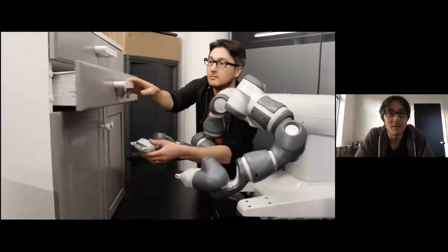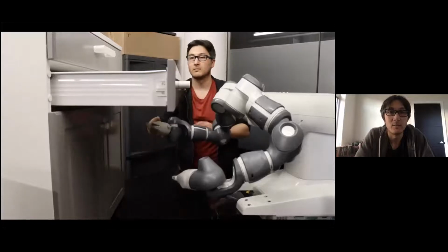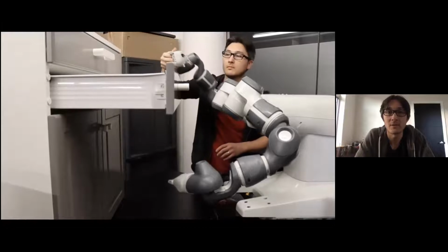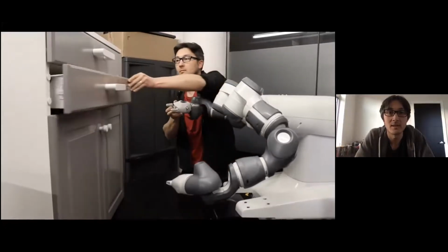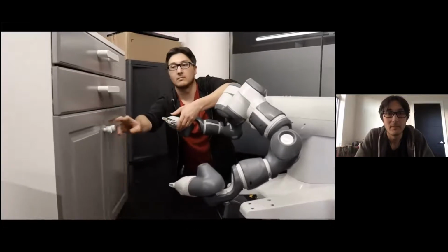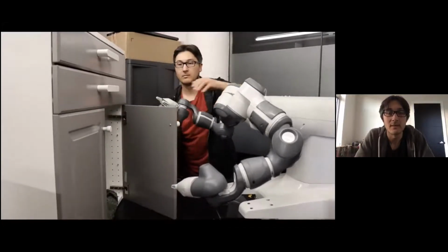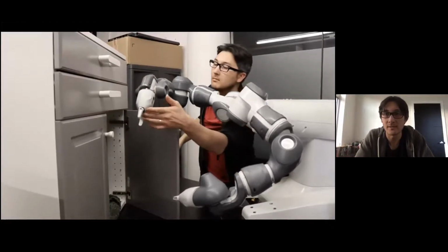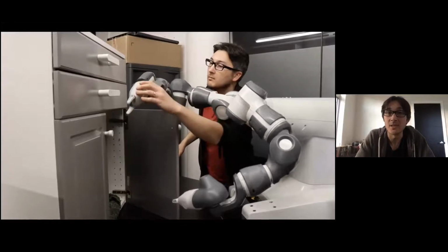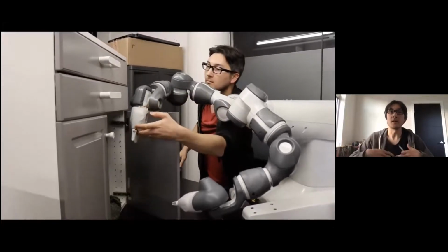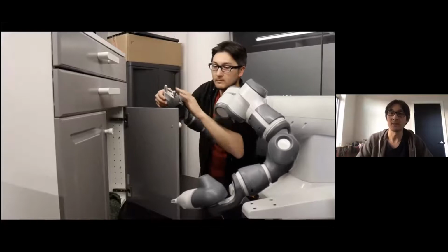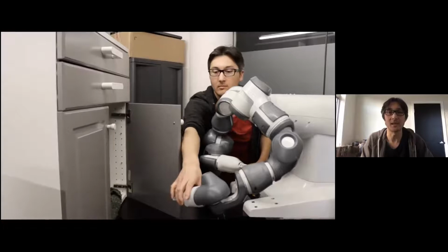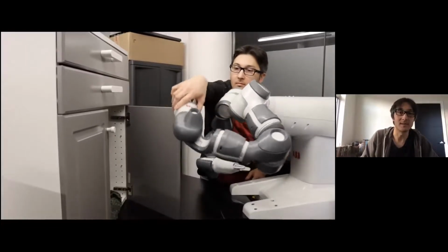And here's another example of being able to just lead the robot through the environment. It's doing automatic obstacle avoidance here, and I'm just kind of tossing it around. And this is one of the things that you can do. It gives a more tangible feel for how these things can be used. So it's not doing any planning, but if you just guide it heuristically, it'll solve all of the problems locally, so that even very simple heuristic guidance is successful.